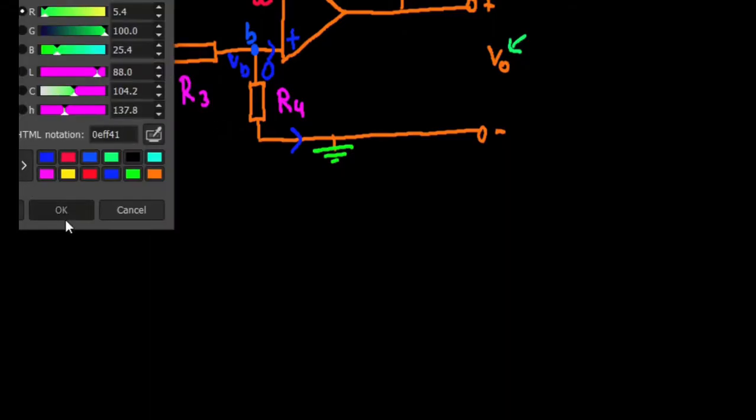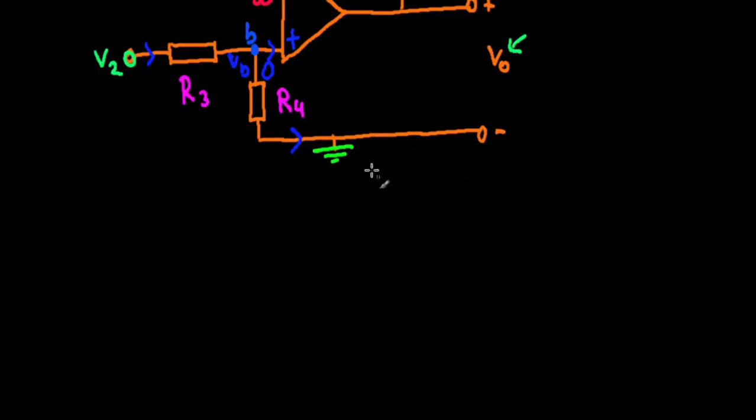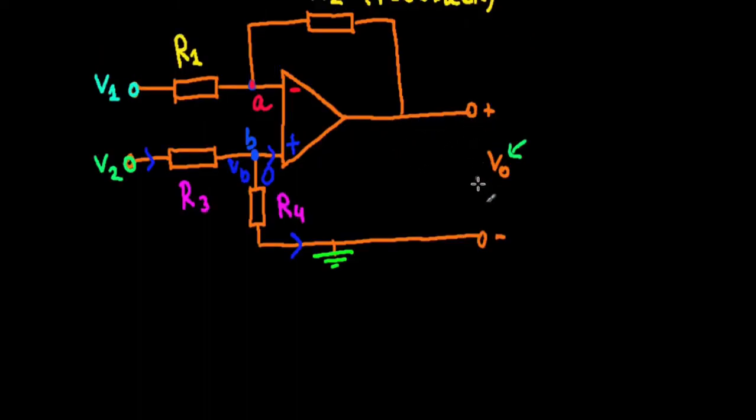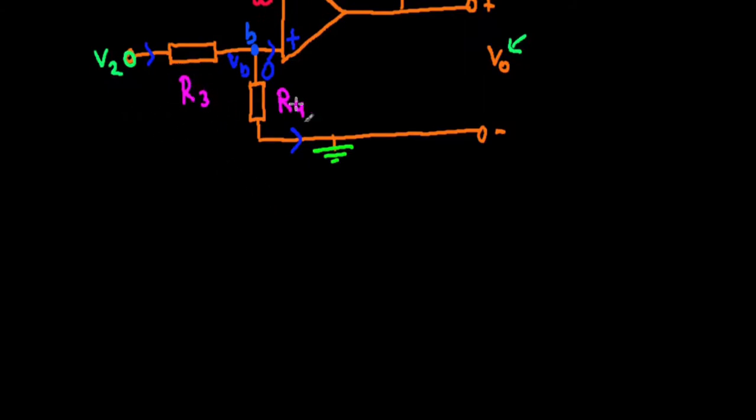One thing is, you might wonder why I'm not saying that this current is zero. Well, it doesn't necessarily have to be, especially if we connect this to something else. This current won't always be zero like it is here, so I'll not do that. But whether it's zero or not, the way we're applying KCL, it would still be valid. So this current entering is the same as this current that's exiting, well, plus zero, but that doesn't matter.